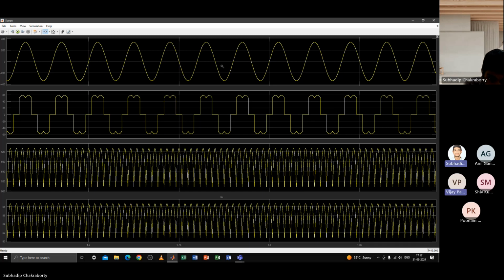Can you comment about power factor then? It is not unity because power factor, I told you, is the product of displacement power factor and distortion factor. Since the waveform is somewhat distorted, your distortion factor is not unity. Do you understand that?